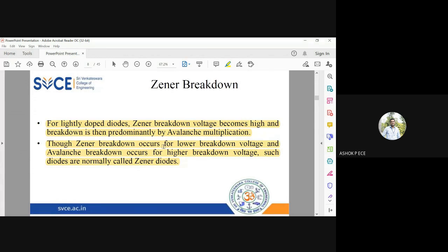So Zener breakdown, as you hear the name Zener breakdown, two things should be coming to your mind. One is very heavy doping of P and N regions, leading to very minimal depletion region width. And because of this depletion region width, the breakdown happens at very low voltages like 6 volt, which is going to produce enormous current without damaging your diode. Okay, without damaging your